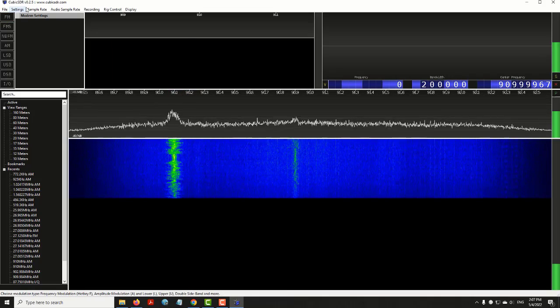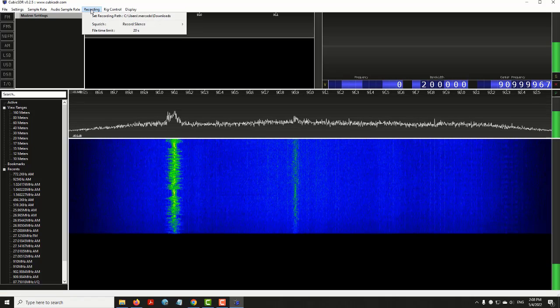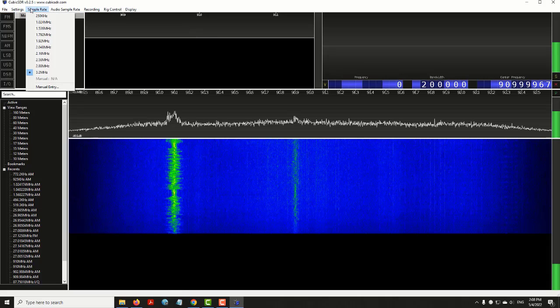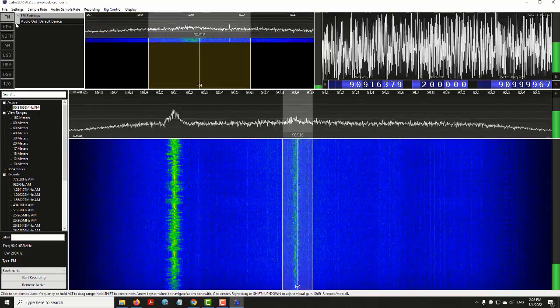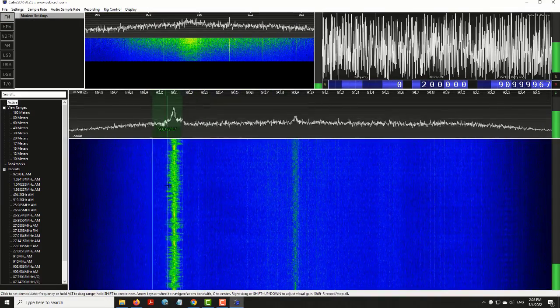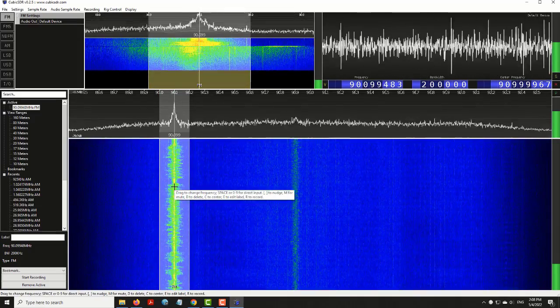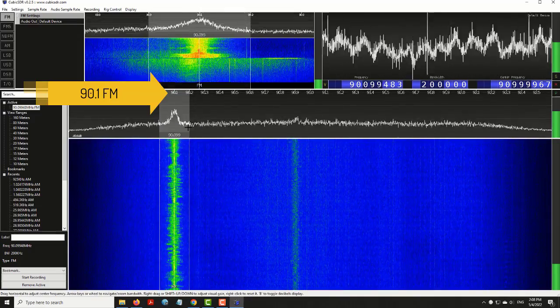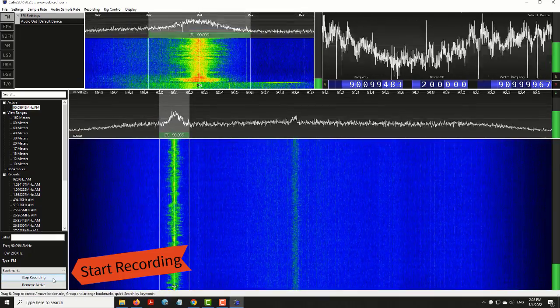Before setting the receiver as FM, let's do some housekeeping. The sampling rate should be well over 400 kHz, which it is. Before exporting the received signal from the SDR, we'll limit the audio file size to 20 seconds. Oops, I set the FM receiver to the wrong carrier frequency. I'll delete that. Let's try again at 90.9 MHz. The SDR is receiving WAMU, a local FM radio station.